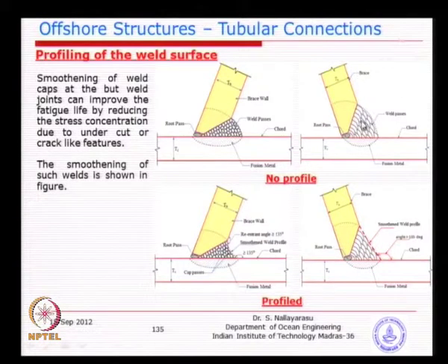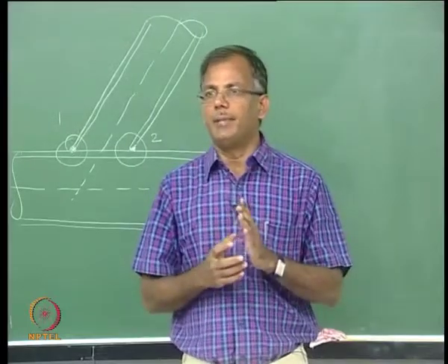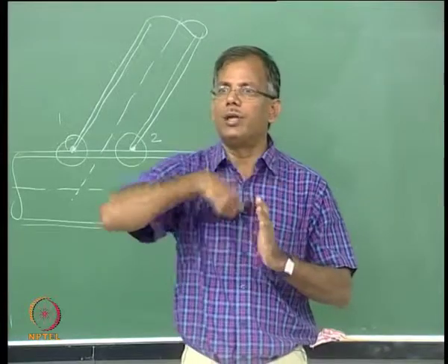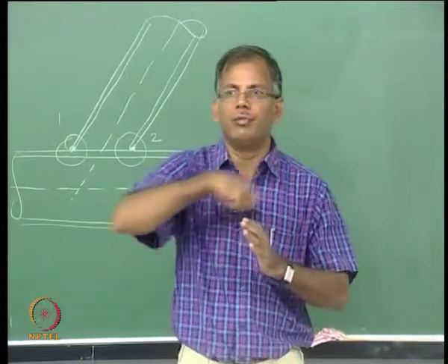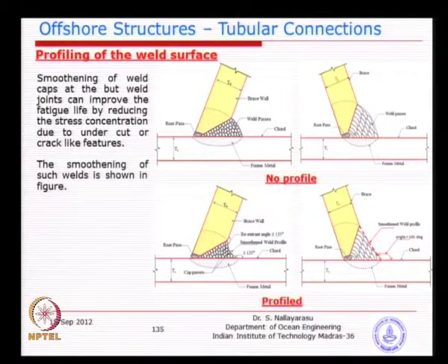And basically you see here multi-pass welding. I think by this time you have an understanding of how the welding is done, because the gap is probably about 50 to 60 mm. So, every time you go around one cycle of welding, second cycle, third cycle, fourth cycle, you will be able to understand the weld deposits in this kind of form. And if you really see in a close view, you will see that the surface is not that smooth.